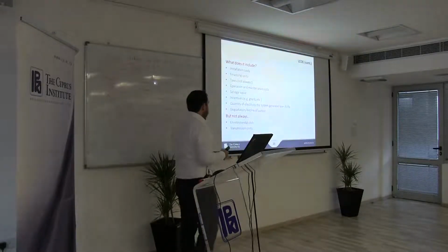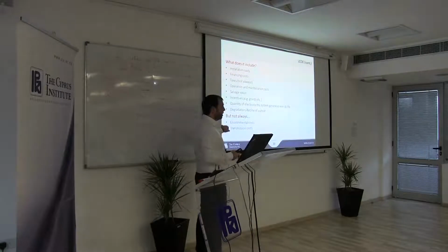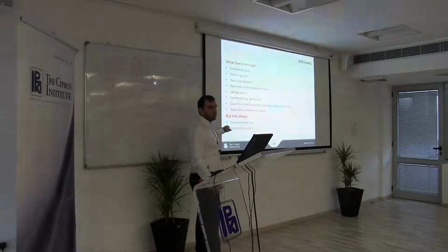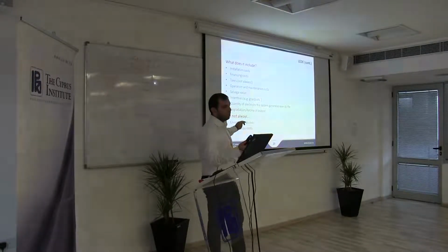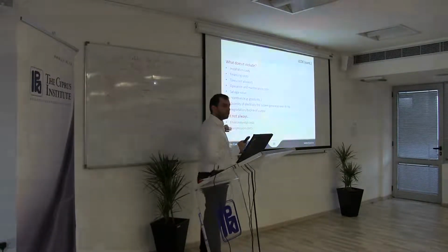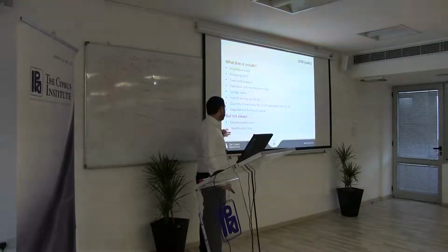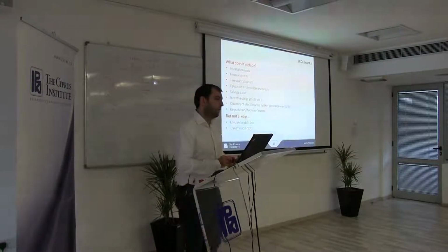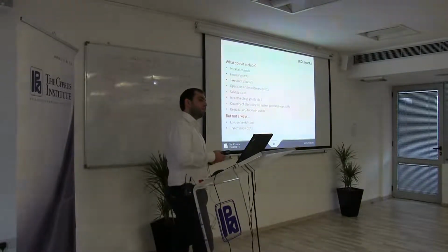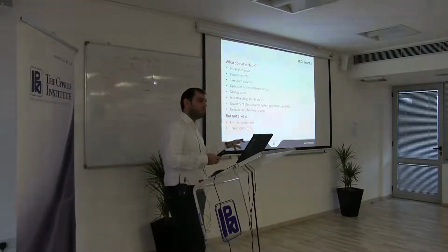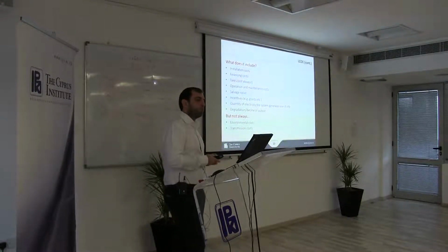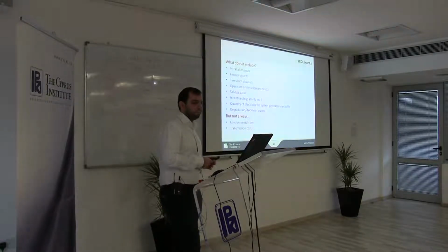And a couple of other aspects that might be taken into account are environmental costs. So for instance, in the case of fossil fuel power plants, perhaps there's a carbon tax. So for each ton of CO2 that you emit, perhaps there's an extra added cost that you need to take into account. And there might be transmission costs associated with the investment as well. So if the plant is going to be situated in a very remote location, the transmission costs, so connecting this power plant to the main transmission and distribution network, might be quite high.